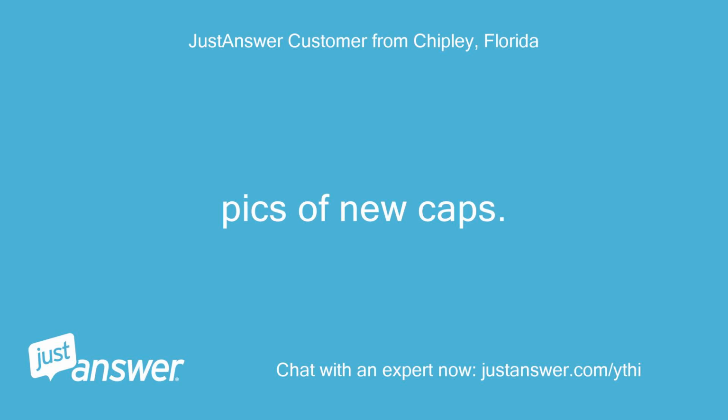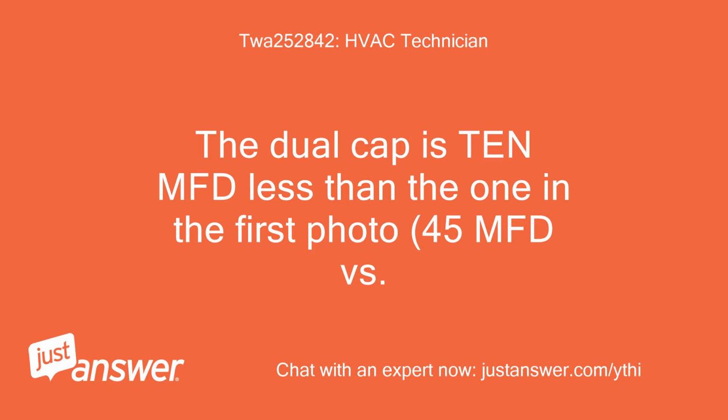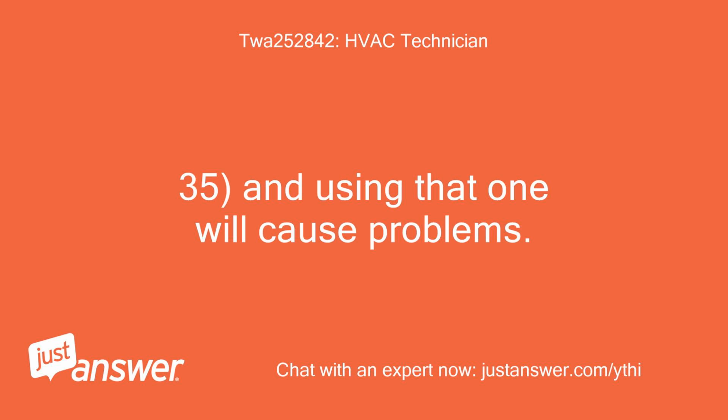Pics of new caps. At the time I did not take a pic of the top of the caps installed, but the new ones are like the installed ones. The dual cap is 10 MFD less than the one in the first photo, 35 versus 45 MFD, and using that one will cause problems.